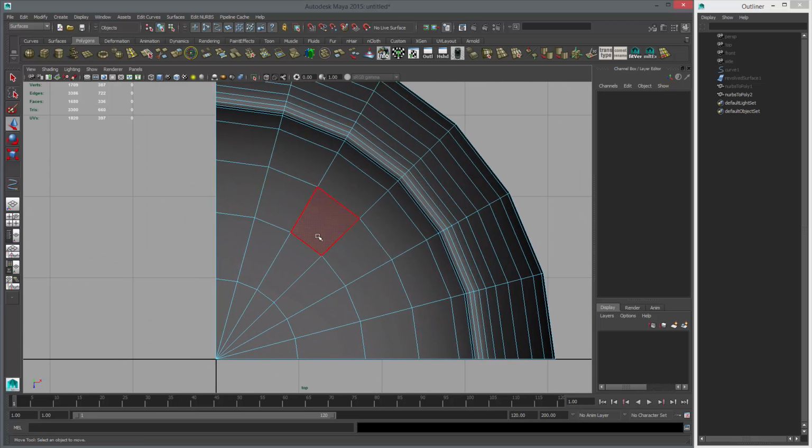Makes it easier. I'm going to use the Multi-Cut tool, and I'm going to drag on this edge, which is basically the first edge loop around the center at the 45-degree line, so right in the middle. I'm going to go straight up and find the closest vertex that matches if we go straight vertical. So this is the one, and then same horizontal.